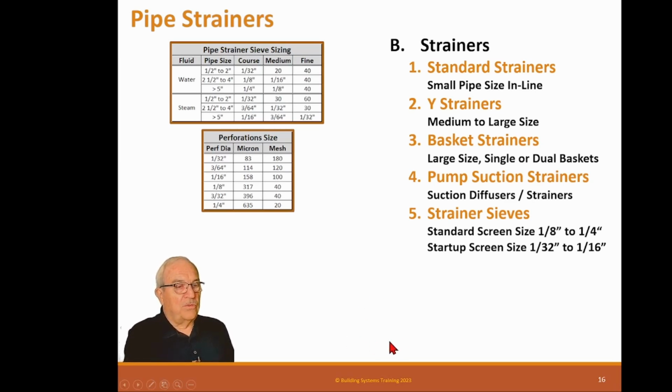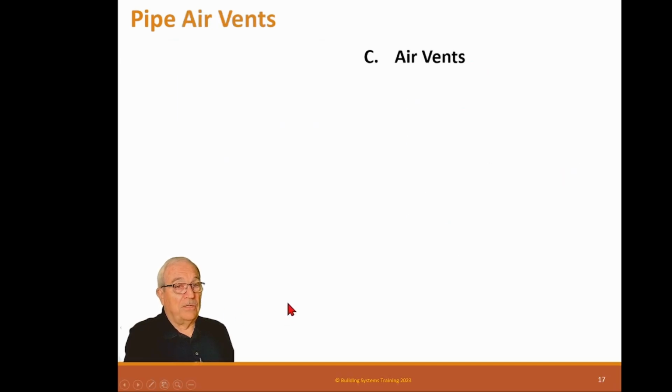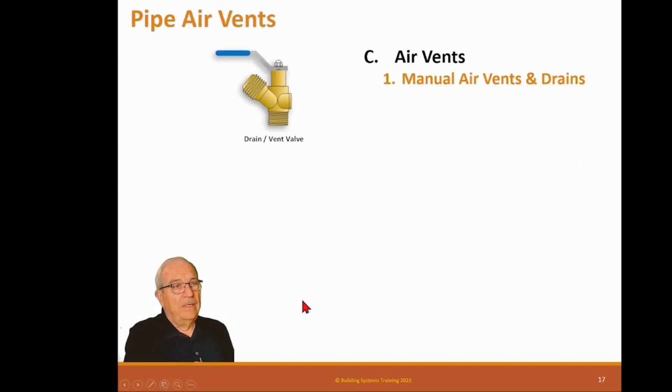So the first thing we do as a balance contractor is ask the contractor, did you remove the startup sieves? And if you get the deer-in-the-headlights response, what's a startup sieve? You need to go make sure they've taken them out. It's really important.